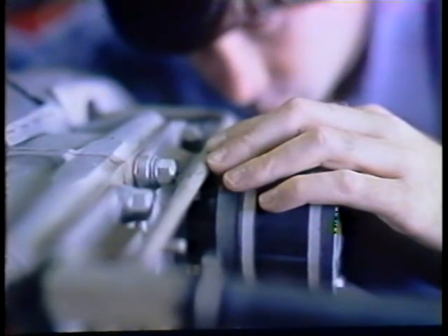Service life of a pump is directly proportionate to the load it carries. And since the technician controls the load placed on the pump, he also is responsible for the length of its service life. Another probable cause of short pump life is an overload caused by airflow obstruction. This is often due to a faulty or plugged filter within the system.